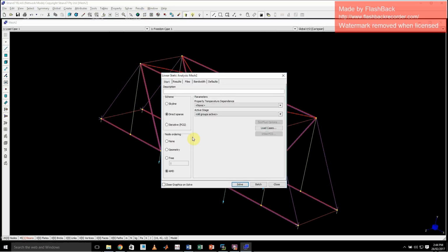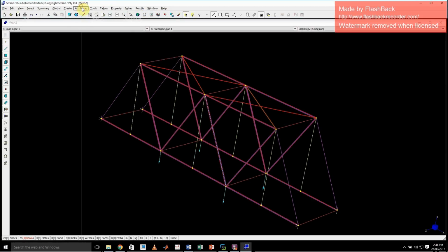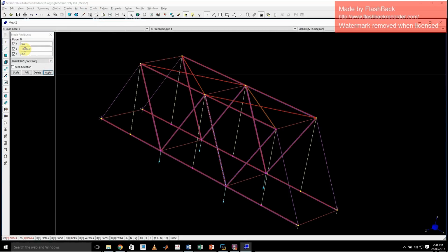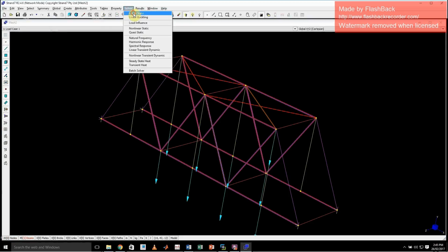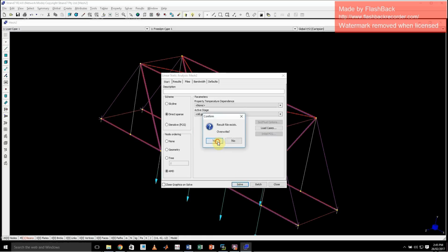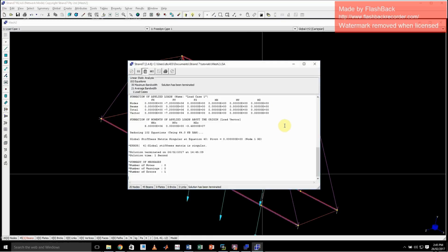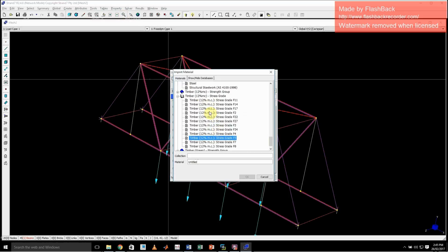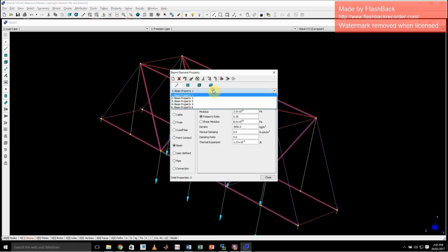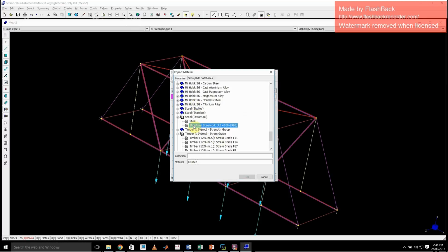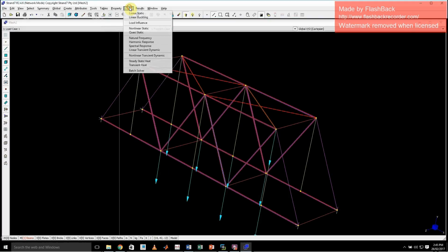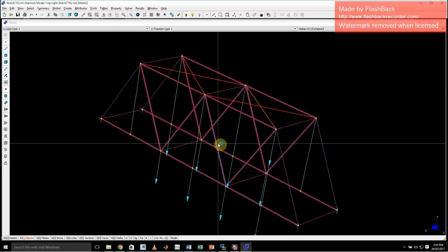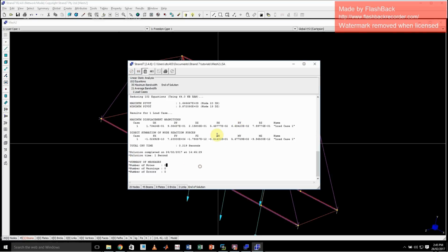So if you come in and you change these loads, so we go attributes of a node, force, we grab these and we put in a couple more zeros there, I apply that, I go solve, linear static, solve, yes. I didn't put my properties back in. As I said, this is the one that always gets you, it just got me. There we go.